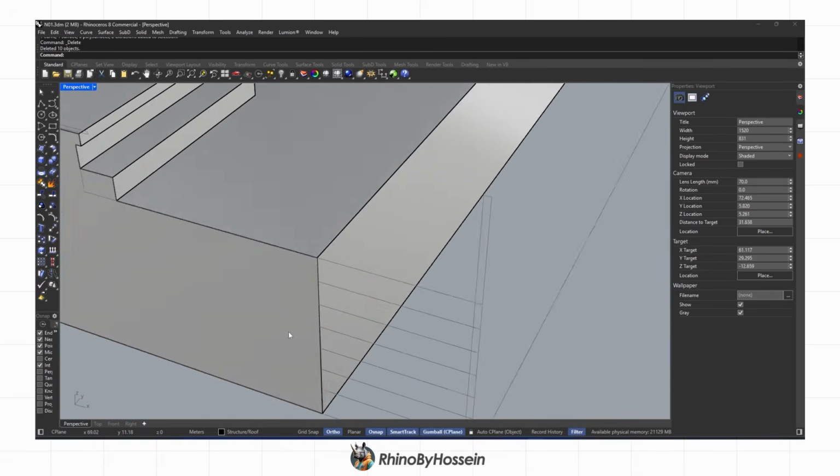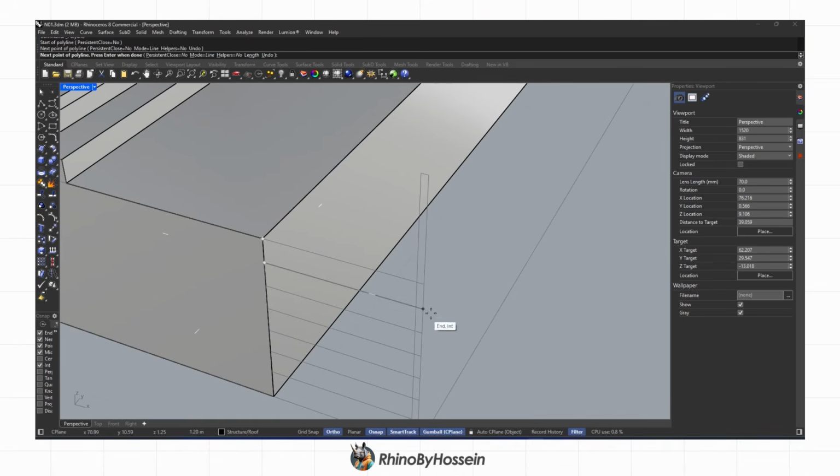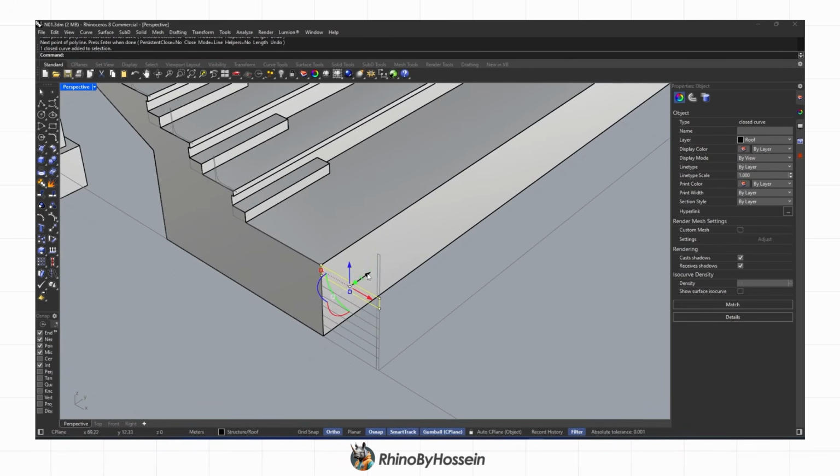Alright, now let's move on to modelling the stairs. I won't repeat the layer management at every step. By now, we can assume the project layers are fully organised and structured. Using the section we prepared earlier, I set the dimensions of the stairs. The landing is 120 centimeters wide, and each step is 35 centimeters deep.